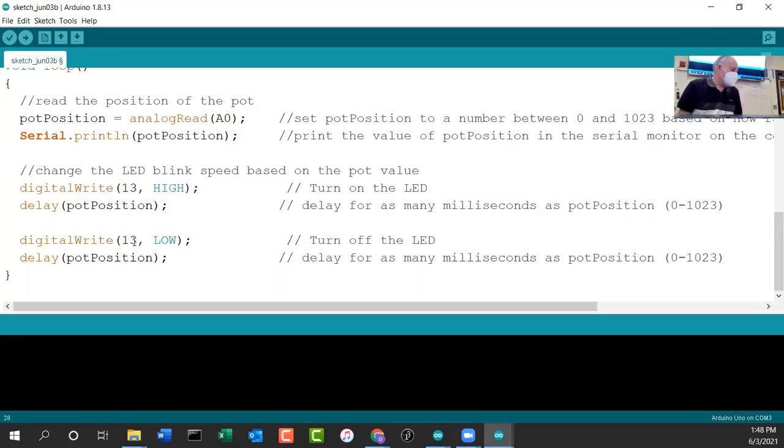So I'm going to plug this into my PC. And you can do the same thing certainly with your Arduino board with your Chromebook. Okay, so here I haven't loaded the program yet. I'm going to load the program. How do I do that? Well, remember, we're not using pins 0 and 1 on this one. Pin 0 and pin 1 on the right side of the red board, remember, those were getting in the way. Every time we tried to upload a new program, we'd have to unplug those. Well, we're not using those pins this time, so we don't have to do that.